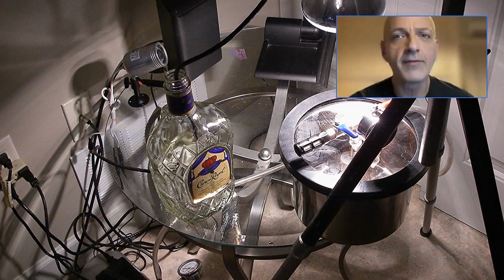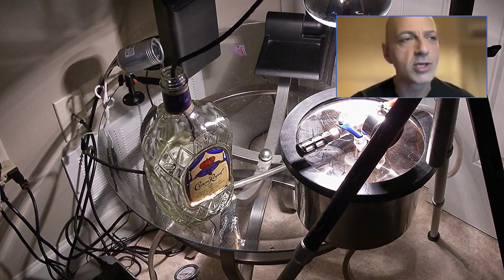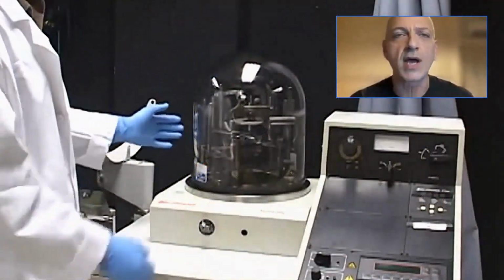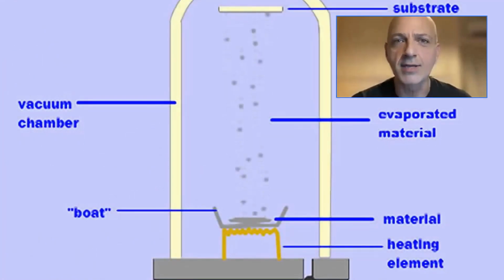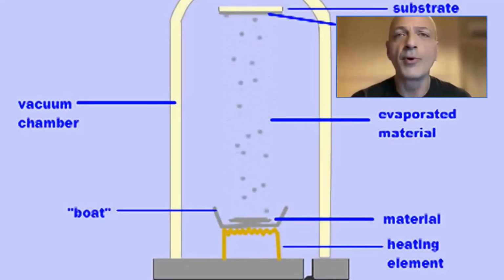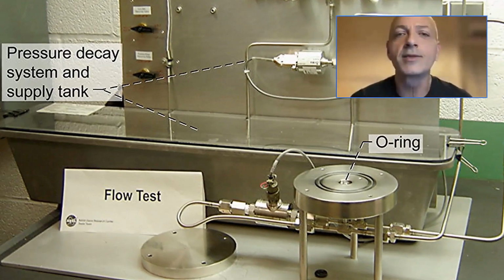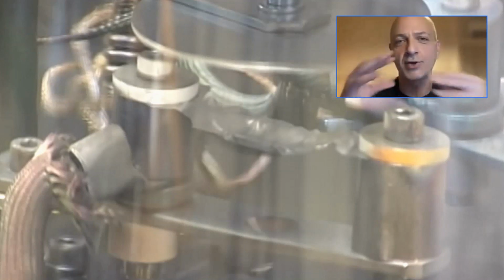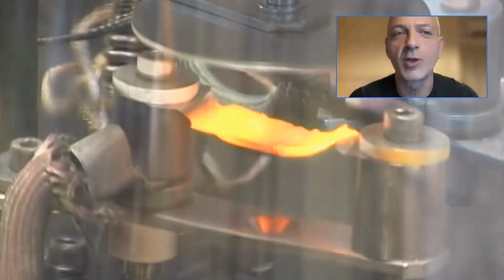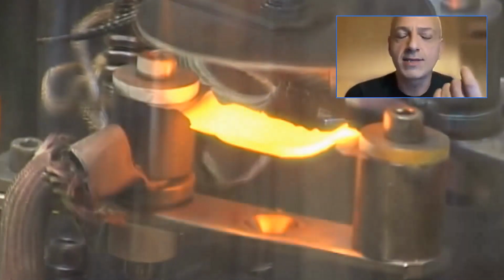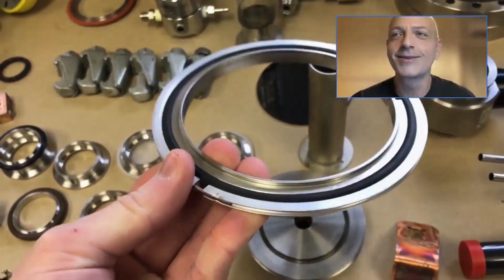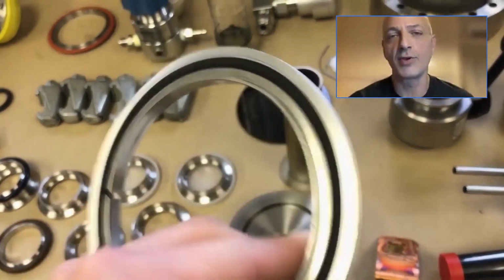I think you did them a favor putting a vacuum as low as 10 to the minus 3. That's basically nothing. From 10 to the minus 6 upwards, everything starts degassing. Rubber degasses, even stainless steel degasses a little bit in the beginning, with oxygen molecules inserted in the crystal lattice. We heat it up so that it spits out the atoms from there as well. But structurally, at least, stainless steel can hold. But rubbers and rubber gaskets are useless in that kind of vacuum.